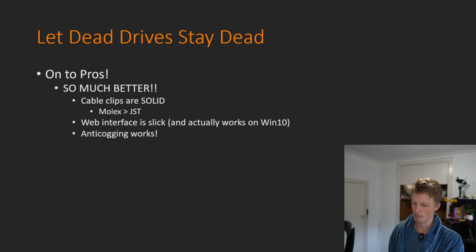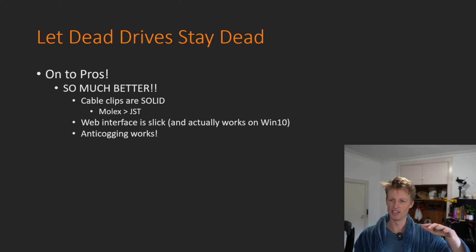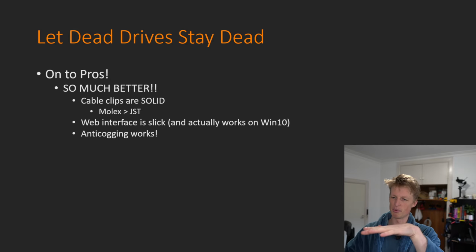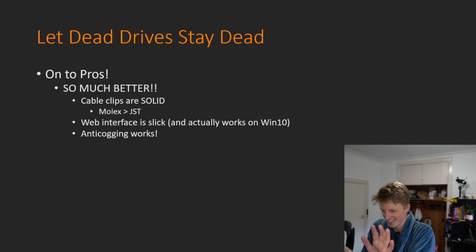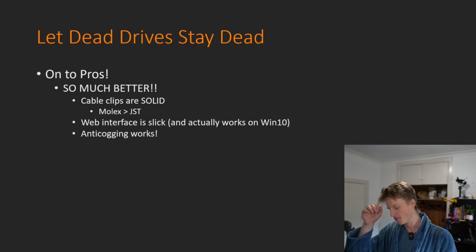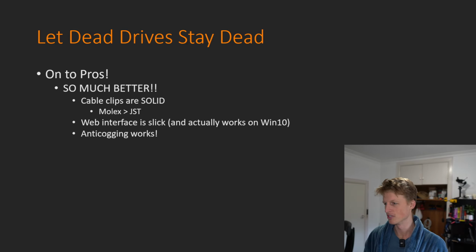But this process means that I'll have to separate the motor from the linear actuators, which will probably mean having to restring all of the linear actuators. So I'll have to de-string them, separate the motor out, do the anti-cogging process, not touch the encoder that's attached to the motor at all. I don't even know what's really connected there, but leave it alone as much as I can, and then restring everything, which I think will be a full day in and of itself, but I think it will be worth it, because having a nice, slow, smooth control will be so sick.